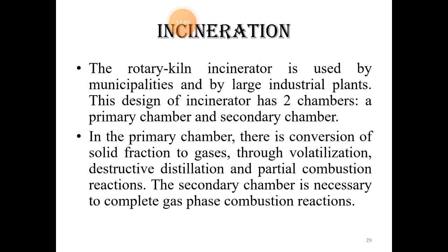There is another incinerator type called the rotary kiln, which is used in large industrial plants. It basically has two chambers, which are called the primary chamber and the secondary chamber. The primary chamber converts the solid waste into gases, whereas in the secondary chamber, the gases are subjected to a combustion reaction, which is further utilized for the generation of electricity.